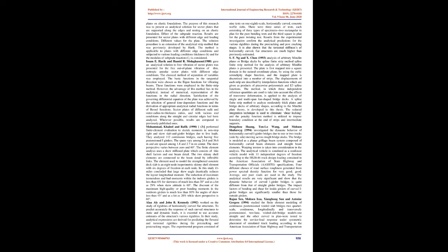The analytical vehicle is simulated as a nonlinear vehicle model with 11 independent degrees of freedom according to the HS20-44 truck design loading contained in the American Association of State Highway and Transportation Officials, AASHTO, specifications. 4 different classes of road surface roughness generated from power spectral density function for very good, good, average, and poor roads are used in the study.